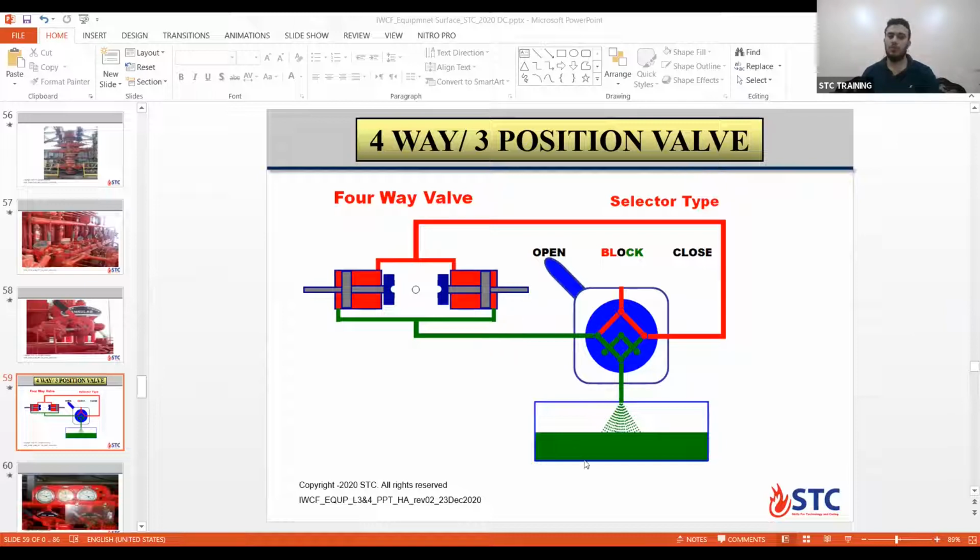So in case we need to make a close function, after pushing the master valve, then close, for example, for the annular, the fluids are taken into the closed chamber and start pumping to make a seal around the pipe, okay? And once we need to open, we start pumping in the red line here.